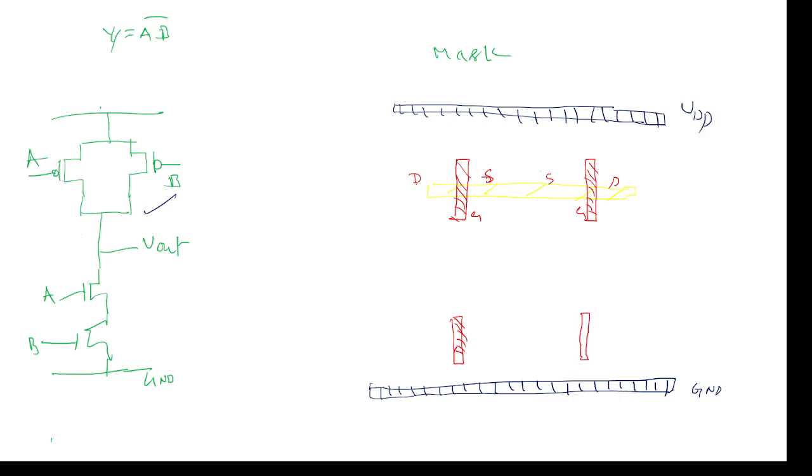Both ways we can draw, even horizontally also. So that's why I'm going for green. Originally it is one transistor, but I'm extending it, this is one more transistor. Now the green symbol is the N diffusion symbol. Right side lines, and the gap between the lines is very small. Now I am assuming this is source, this is gate and drain, and this is source, gate and drain.